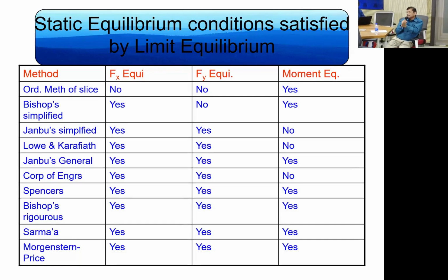Like we are saying, translational needs a critical check, like the liner we are putting in the slope. Definitely we are causing a weak zone. As I mentioned to you, identify the weak zones. The liner is a weak zone. So there are some methods which treat that better. But if you have completely homogeneous soil, Bishop is the best.